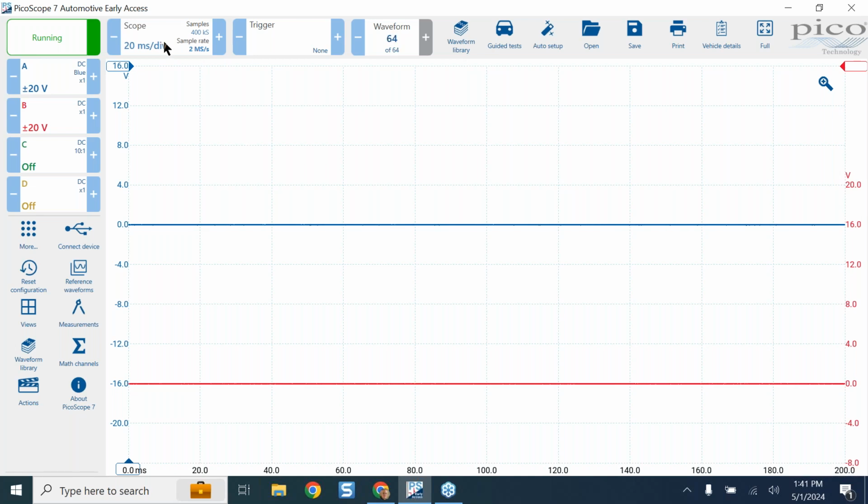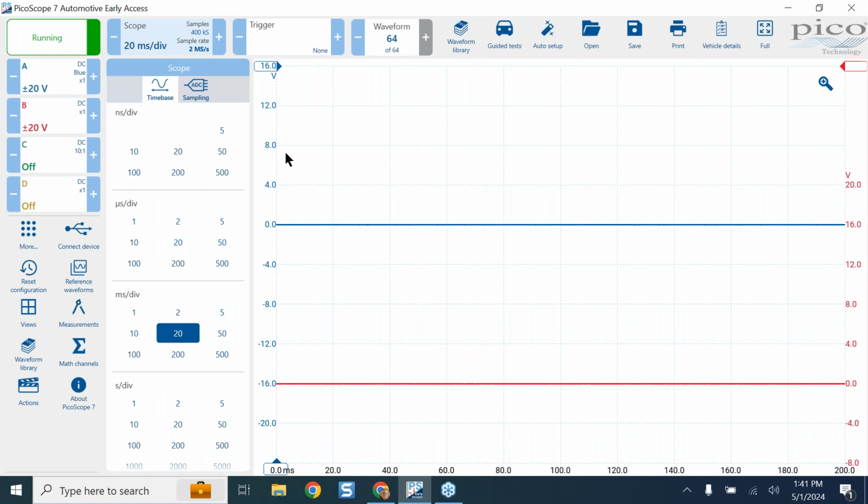So I'm just going to go from left to right here because of the scope and where the sampling rate is at. Sampling itself, I'd like to spend a little time with next month. Sampling can get pretty complicated, but I'm going to point out a couple of things that I do get asked about, especially a couple of years ago when we removed the waveform library from PS6, we obviously gained a lot more users in PS7, and we had several common questions. Probably the most common was about sampling. It was about, where is my properties tab, or where is my sample interval at?